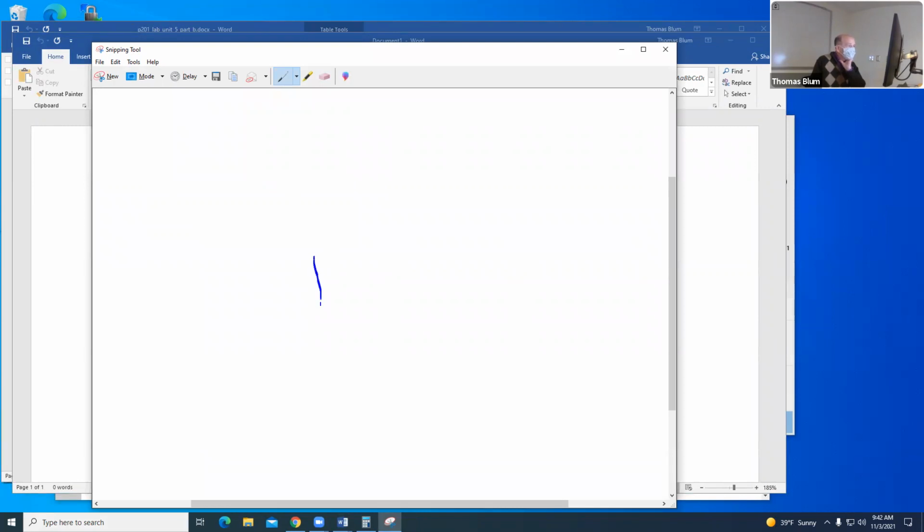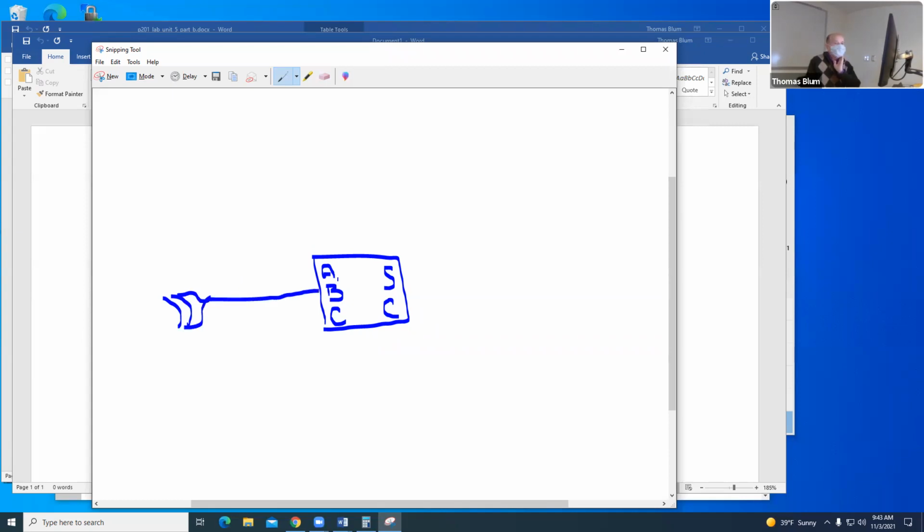I have my last adder. Here's a full adder. There's A, B, and the carry in. And here is the sum going out and the carry out. And there's some exclusive OR into the B. That's about negating the number, and I'm not interested in that. I'm interested in the action of the addition.